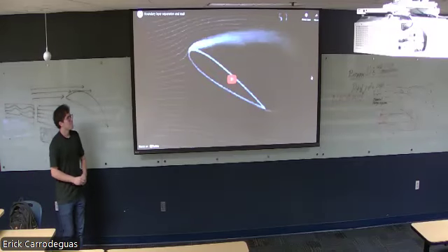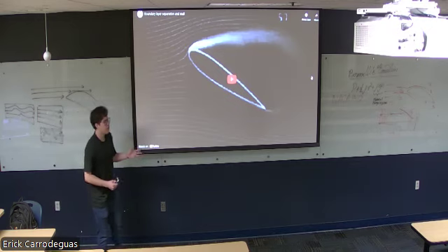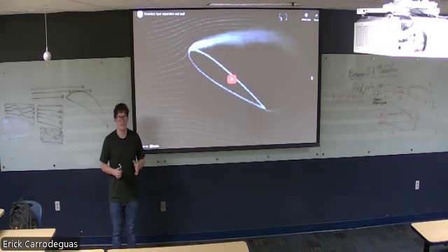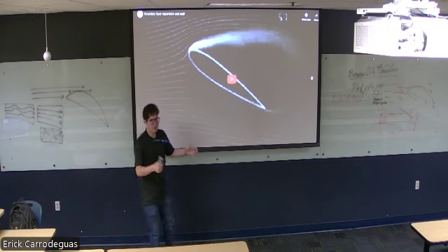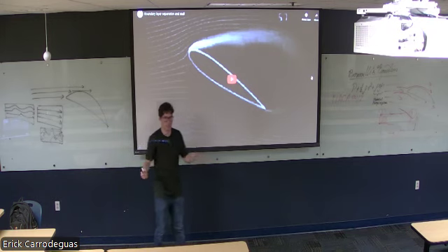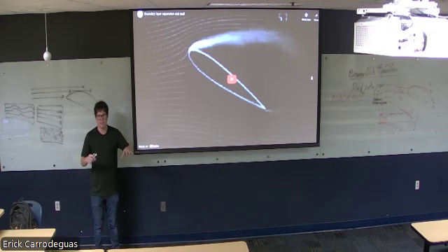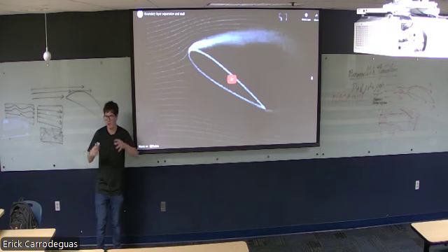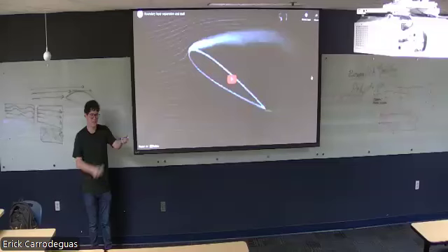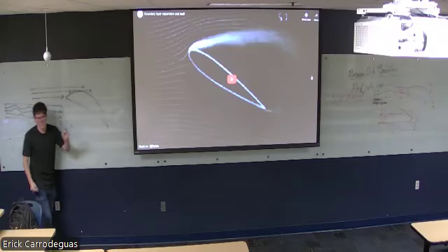But he's a flight test engineer. So what he does is that if you ever go into a plane where a flight test is being performed, you're going to see these big barrels of water all connected with pipes and everything going crazy. What they're trying to do is change the center of balance on the planes and see when it will stall if you're carrying something here or there, or if you shift the center of balance all the way to the back. If you shift the center of balance to the back of the plane, you're just going to start doing backflips in the air. So just remember that.